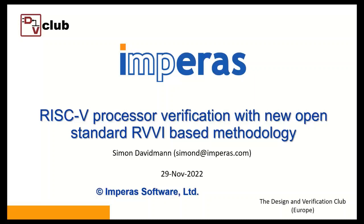Well, the first thing is that you need to go to the GitHub, which I mentioned. It's under GitHub, RISC-V verification, RVVI, and read through that. It provides the source of a SystemVerilog interface so that you can include that in your test bench. It defines all of the types of signals that you need to use. And it depends on the type of verification that you're trying to achieve.